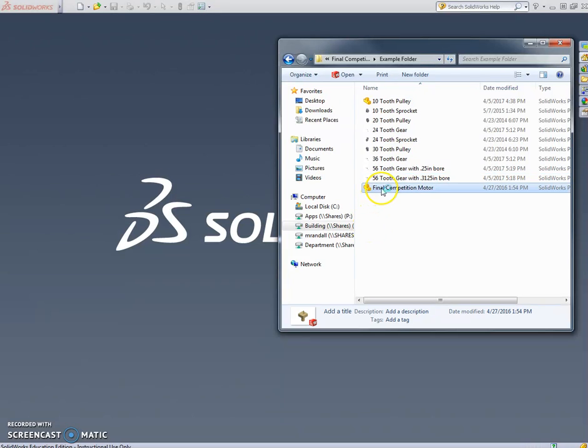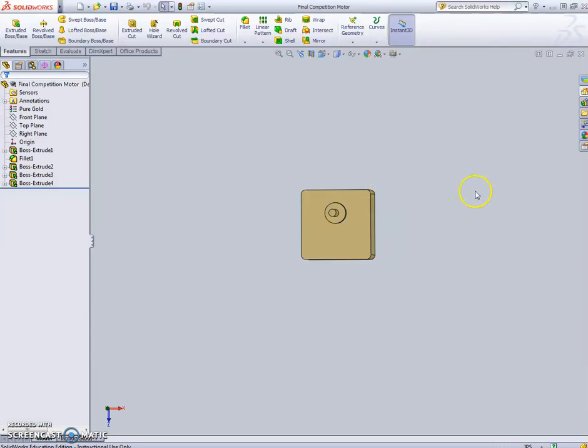Okay, you also need the motor. Let's open that up. Here's what it looks like. It's not gold in real life, but that's the color that one of my former students who drew this up decided to make it. One thing I want to mention, this is actually a motor, that's the motor part, and a gearbox. This motor itself is a lot like our SumoBot motors. However, it's bigger and it has more power. And this gearbox gears down the motor quite a bit, so it makes the output shaft go a lot slower than the original motor shaft.